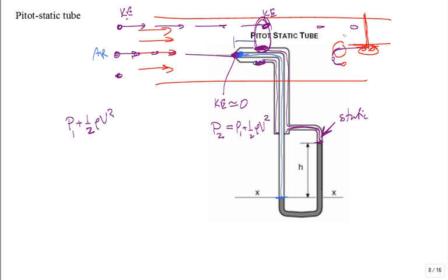And you wouldn't want to design it with a blunt edge, because with a blunt edge you would get more separation coming off that edge, and then it would have to be delayed longer down the tube before you had the good static pressure. That make sense? Okay.